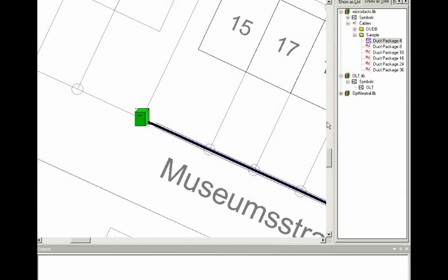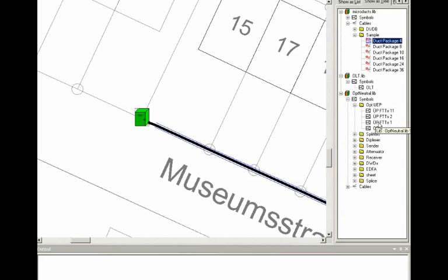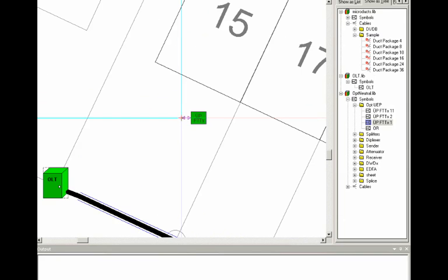The next step is placing the ONTs in the houses, and we're going to take a 1 fiber ONT from the library, and to place it nicely we want to align it with the house boundary. Now you can rotate it using R by 90 degrees, or you can use the D and S keys to fine-tune the rotation. Of course, there's also a helper function. You just move the mouse with the object on the boundary of the house and press A to align.